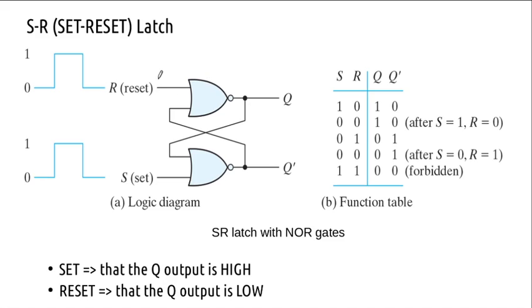If I put 0 on this pin and 1 on this, what happens? I'll assume that this is 0 and this is 1. What will the feedback be, starting from this side? Then this comes here, 0 0, output 1 came, replaced here with 0. So 1 is shifted here, 1 and 1, output 0, reset.